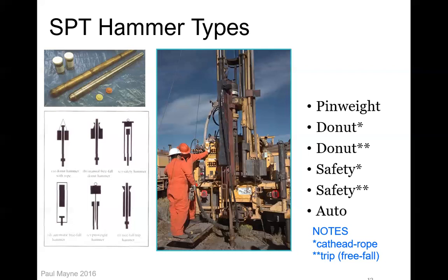They're skipping every 5 feet and, like with the auger, they're just circulating soil. Yep, exactly. With the auger method, where the soil comes up dry, that's beneficial because they can clearly see when the soil layers change. So in that case, they could be like, okay, how deep are we?